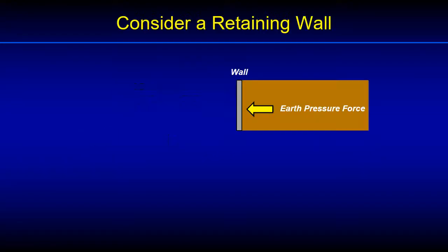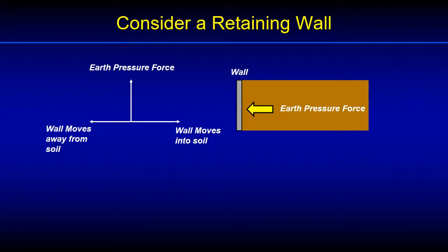Most geotechnical engineers have some understanding of the concept of earth pressure associated with retaining walls. So consider a wall which has magically been placed into the ground to replace the soil on the left without disturbing the soil on the right in its natural state. The pressure acting on the wall will represent what we call an at-rest condition, which is really the horizontal pressure in the ground before the wall was placed and associated with no movement.